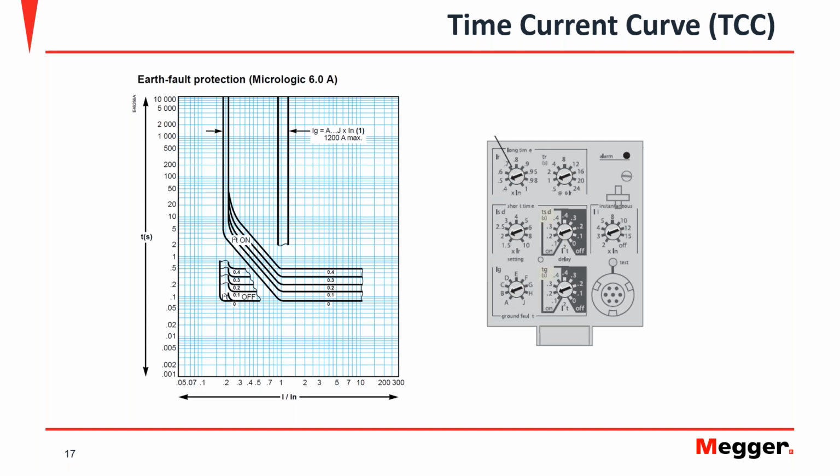Hey, Jason. Back over to Dinesh. Dinesh, what size and quantity of cables can the SPY unit take? I think that's a very good question, because the person who asked must have performed this kind of testing out in the field, because the size and the length of cable would directly impact the amount of current you can get out of the test set. And as you guys know, Daniel did cover that, where he covered the impedance of the circuit.